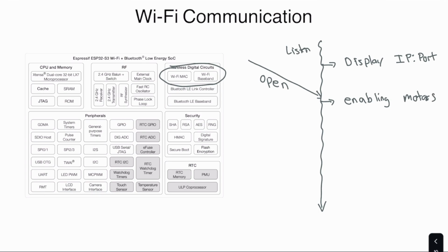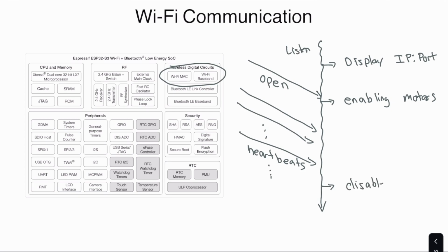And of course, the way that we're coding up our communication is we'll have a sequence of heartbeats, so that we know no communication has been lost. And after a certain timeout, we'll make sure to disable the motors. We could also disable the LiDAR and disable other systems. There's not much risk of leaving those running though. The biggest annoyance there would be that they just draw power when they don't need to be.